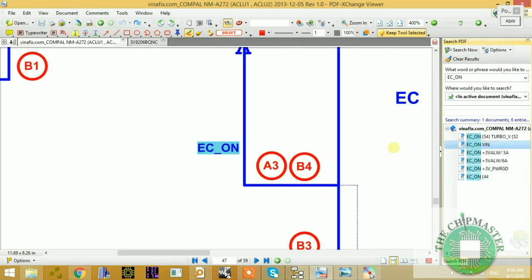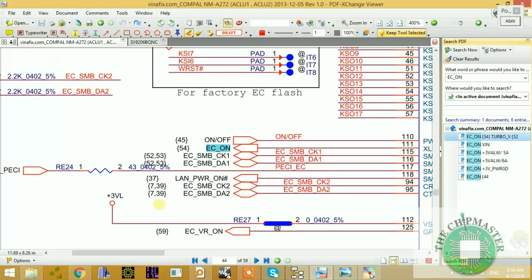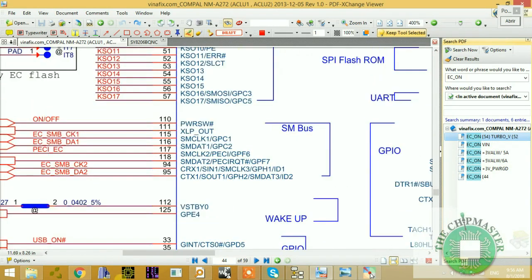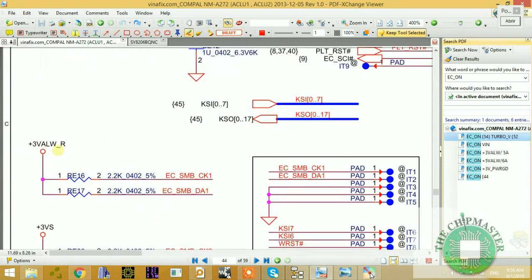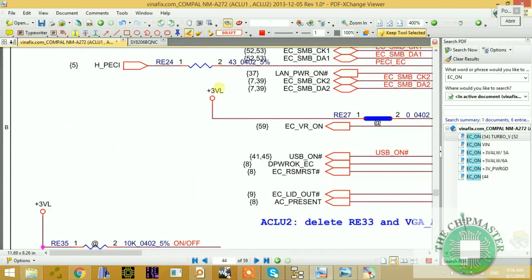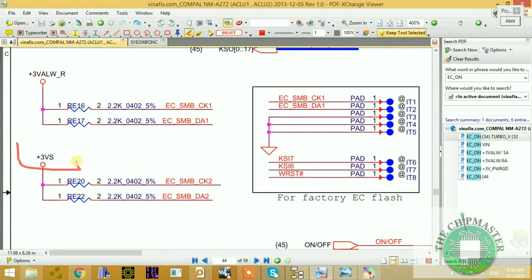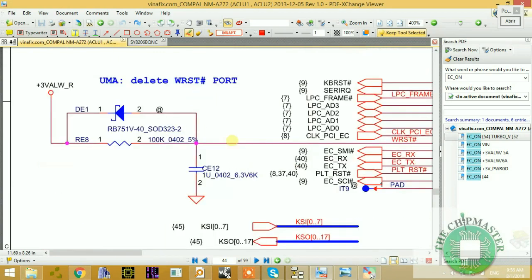And it is coming to power, to turn on the chip, to turn on 3 volt PWM. Right, remember, PWM voltage is different from a linear voltage. This is a PWM voltage, right? This is a linear voltage. This is a switched voltage. This is after the board is being powered on, fully on, S0 state. Remember that. Okay. All right, so this is the process again.